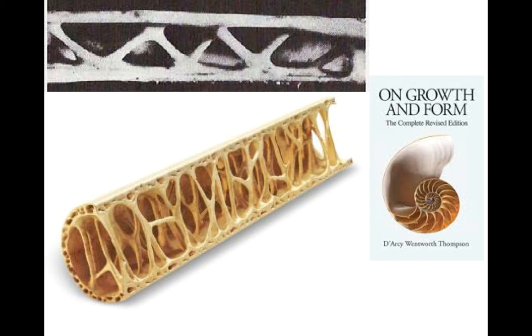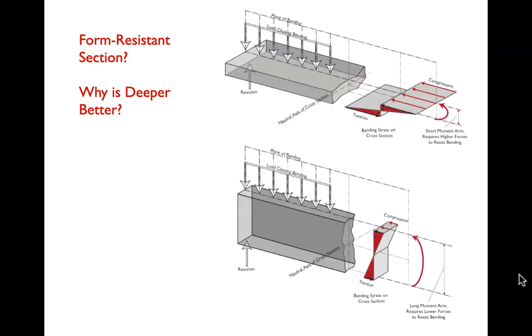Now, this gives rise to the principle of the neutral axis, where if we want to be really, really efficient about designing our beams, we can actually scoop out material that's being lazy. If we go back for just a second, think about the material that's right around the middle in both of these beam sections. That's not doing much. Those fibers are subject to not very much stress at all.